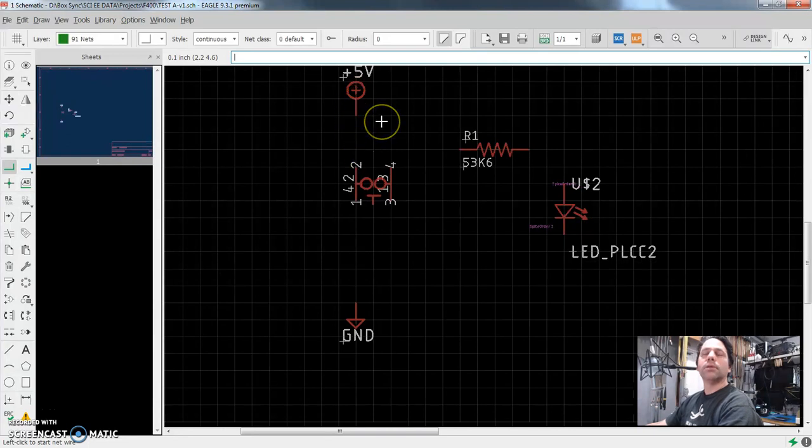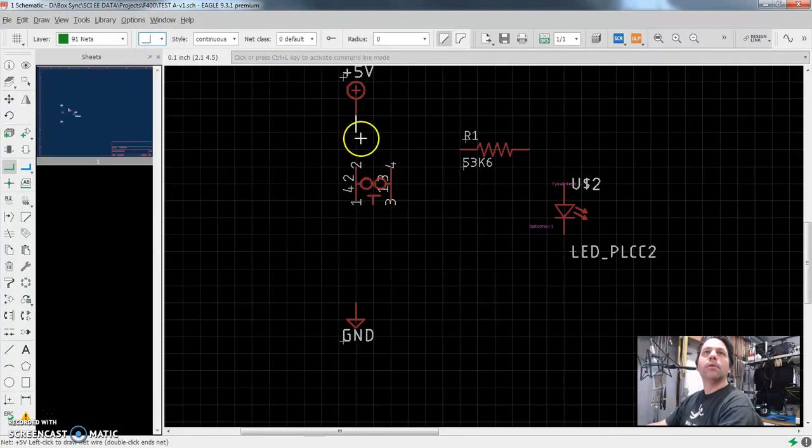And a net is essentially any group of connections that have the same name, that are on the same node of the circuit. So I will just simply click here, and if you notice, this thing is automatically making right angles, and it's trying to support me as I go to these different possible places that terminate the wire. As I right click, I can change the shape of that wire based on this little menu here. But this one just goes straight down to the switch, and we like that.